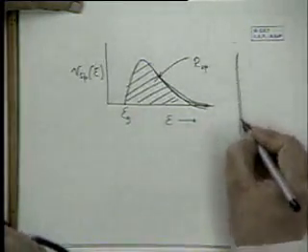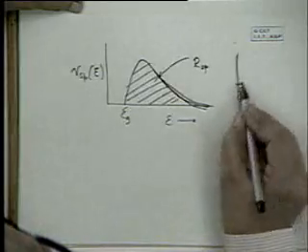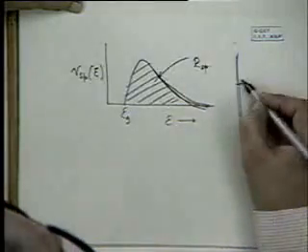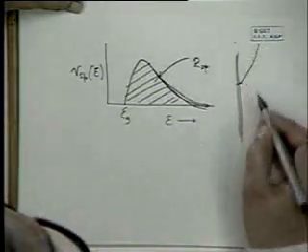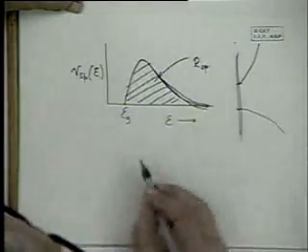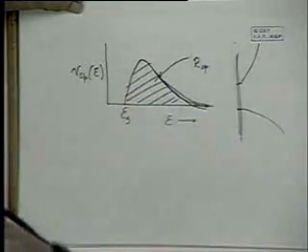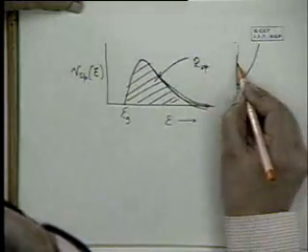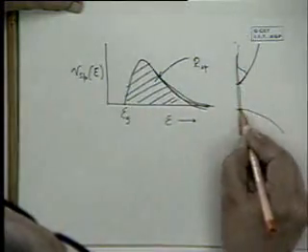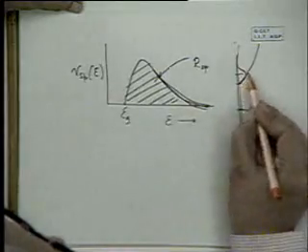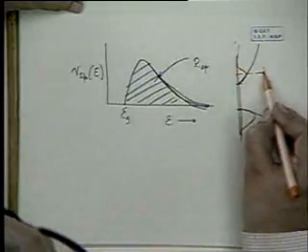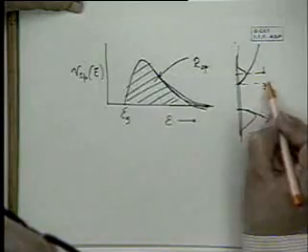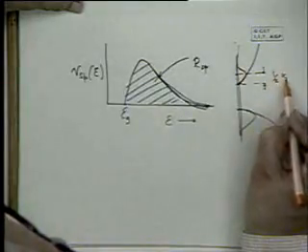Because remember, when we look at the semiconductor, this is the conduction band. The density of states goes, say, something like that. The valence band density of states goes something like that, and the actual carriers that are occupying the bands, this is the maximum, which is typically half k_BT.